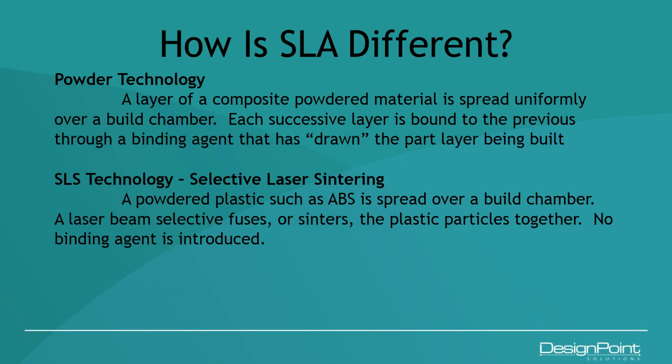And instead of using a binder to hold things together, it actually uses a laser beam, similar to SLA in the sense that it's using a laser beam, but in this case it's not curing it, it's actually fusing the particles together using the energy of the laser to bind everything together to make it in the final shape that you're looking for. The nice thing about SLS technology is the final result is a pure plastic part. There are no UV curing agents in it. There are no binders. You literally have what is as close to injection molding capability as you can get without actually doing injection molding.